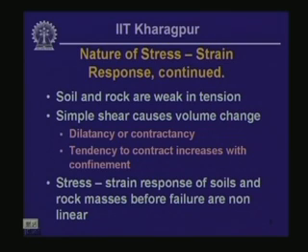Second aspect is simple shear causes a volume change, and that was evident from the triaxial stress strain data that we schematically presented near the end of the previous lesson. For application of shear stress, we were also having a change of volume, and this type of behavior of shear volume coupling is called dilatancy or contractancy.